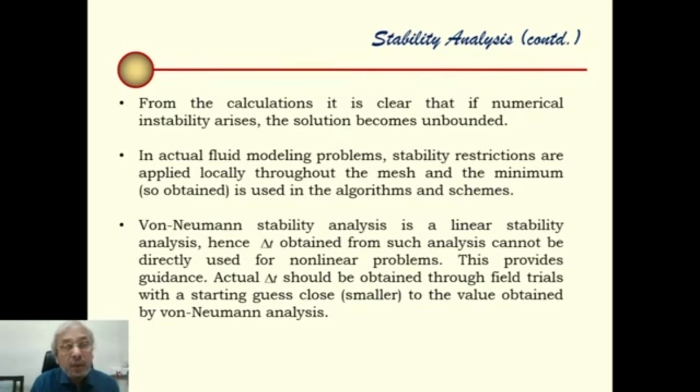We have seen earlier also that in order to increase the accuracy, we have to make the grids finer. But not only making grid finer will raise the formal order of accuracy, you have to go also for higher order schemes. But higher order schemes we cannot go arbitrarily. We have to obey always the consistency related restrictions. Having done that, we can go for higher order discretization method.